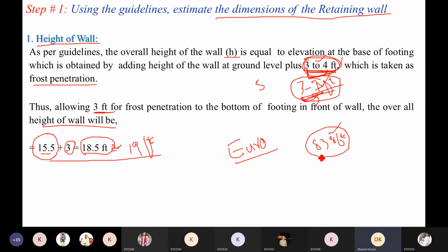So they decided that they still had to dig deeper. Then they decided to dig the pile foundation to 1.5 times the height of the Burj Khalifa. So the foundation of the Burj Khalifa is 1.5 times its height below ground. Because at that particular point they got soil which is hard enough to sustain the total load of the Burj Khalifa, and the pile foundation used in the Burj Khalifa is a bearing cum friction pile.